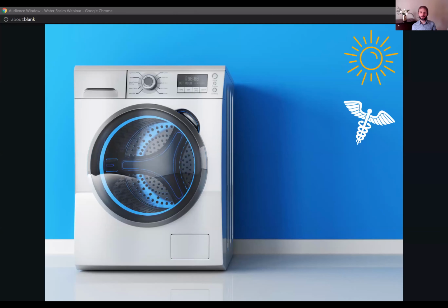The other thing to consider with energy is peak load. So again, reminding you, when we talked back at the energy pillar, you want to make sure that you've got not only a water saving device, but one that also can be run at off-peak times on a timer so that it will run later. And the front loaders always, on average, save more water than the top loaders. But we've got the little health sign there because what happens on those front loaders is in the lip, water can get caught. And if you keep the door closed on a lot of these models, it can build up into mold or mildew. So watch out for that.